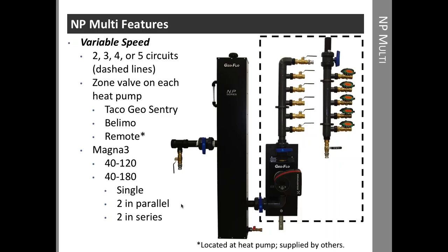For higher head applications, we can use two of these in series, and they're mounted one on top of the other. And in that case, now we can have up to almost 100 foot of head with a variable speed central pump system. Now, they don't talk wirelessly when they're in series, but we still do have the capability of having one pump online if one would fail. So we get not 100% redundancy, but some redundancy out of that application.